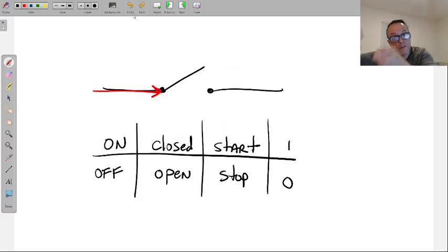If there is voltage here at the load, then everything down the line is closed. Voltage got to the load correctly. The load is not on. The problem is now the load. So it's a way to also understand how to troubleshoot these circuits, and these circuits will get more complicated as you go into motor control and PLC.